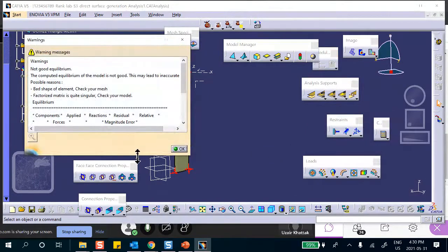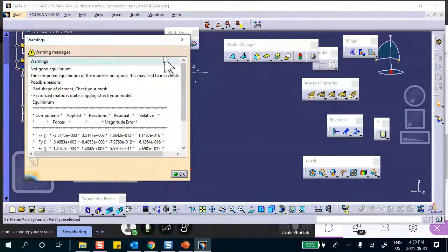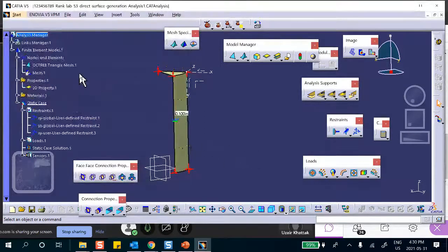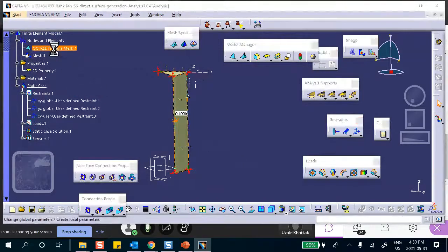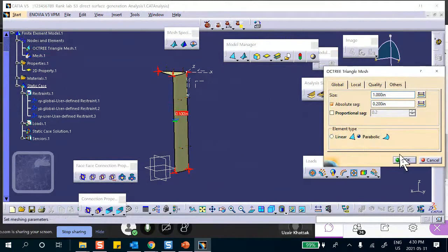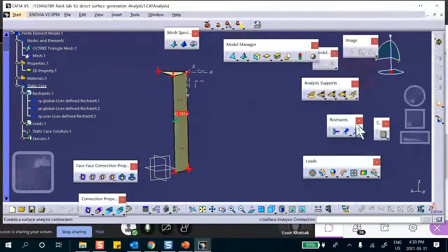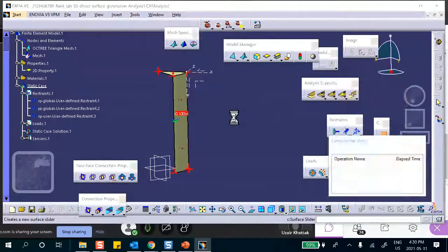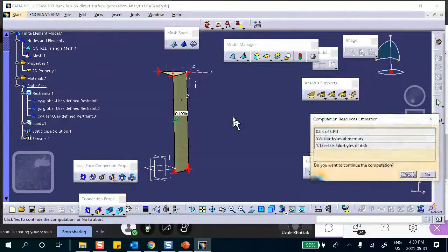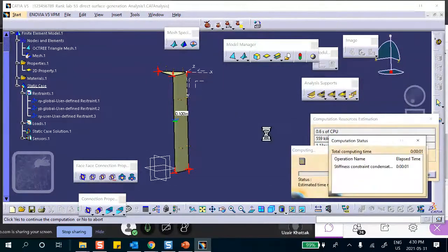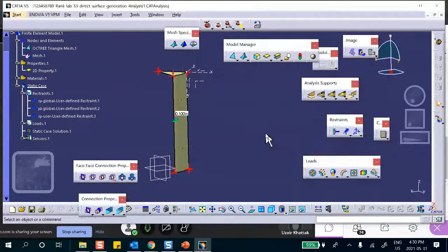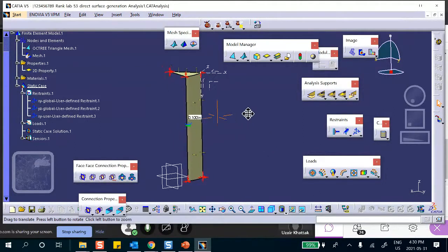Okay, what this is saying is not a good mesh. Basically I have a horrible mesh. That's what it's saying. It's going to show you stuff. I can make it smaller, or I can make it perhaps parabolic. Let's try. This doesn't say it didn't run. It just cautioned you that you may be getting stuff that is, let's try parabolic, see whether, this is a simple enough problem that it's going to run very quickly. We'll see. You see? It said with the first one, that mesh, do it, but you're on your own. Or we don't guarantee anything. They don't guarantee anything anyway.